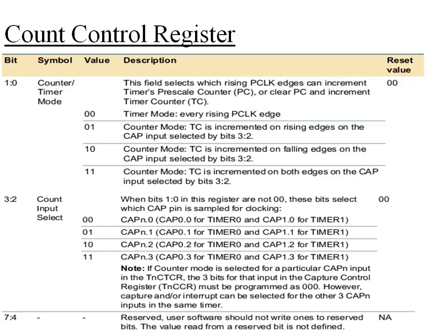Now what are these counter pins? If you are aware of the 8051, there you have the T0 and T1 pins. If you are using the timer peripheral as a counter, then the clock signal is given through the pins T0 and T1, so that it counts the number of clock pulses you give through T0 and T1.